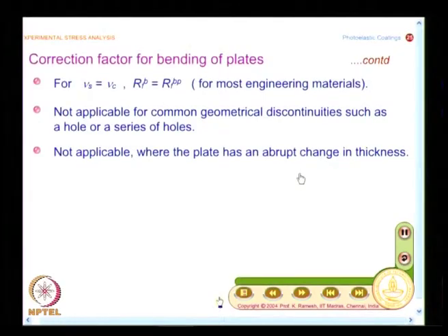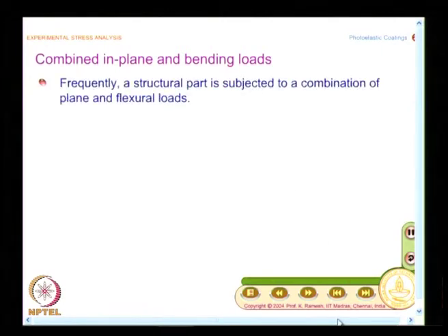This is the way they solve the problem from an engineering point of view, because the correction factor determination becomes difficult. In fact, I am going to show you correction factor for torsion, I am going to give you only the final result. If you look at the development of the necessary equations for correction, very complex. When you go for pressure vessel, it is going to be much complex than what you had seen earlier. We have only developed a systematic procedure for in plane load and also for pure bending. For all other cases, we will write only the final expression. We will take the result from the literature as sacrosanct and use it.